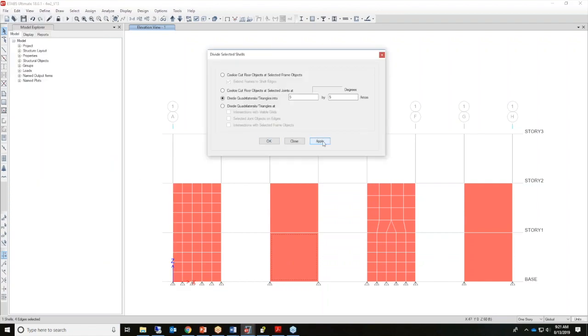And I'll do the same for this one. But I'm going to make a little bit of a change here on top. I'm going to make this 4 by 4. So here we have a situation with some mismatched nodes. That's a very common question as well when it comes to meshing: what happens to load distribution if the nodes aren't exactly matched? We'll get into that in this example. Here we'll do the same thing, 4 by 4 on top, 5 by 5 on the bottom.